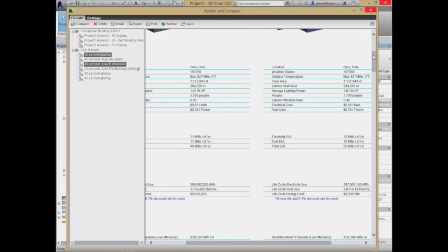So just by using a slightly better grade of window, I can pretty much achieve the same as cutting out half the glass in the building, and achieve a very similar sort of cost. So let's put this into perspective in terms of what it all is. What's this all about? At a high level, we're really just trying to say experiment with different forms, try and figure out what you think the good shape for your building is going to be, and as you're evaluating the different shapes, consider energy use as one of the different factors that you throw in there, as well as all the architectural features that you want to put in there.